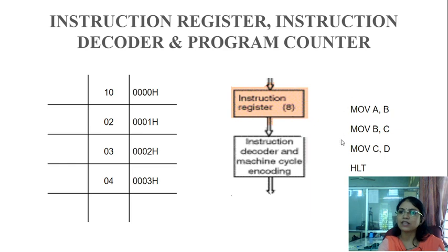This is an assembly level language program, because here we are in microprocessor 8085, we are writing one program in terms of assembly level language. And what is meant by assembly level language? It is nothing but whatever task we want to perform in the program, we write down in terms of some coding language, and that coding language is called the assembly level language. Okay, so here MOV stands for move A comma B. A is our accumulator and B is the general purpose register B. Similarly, here I am using the general purpose registers C as well as D.